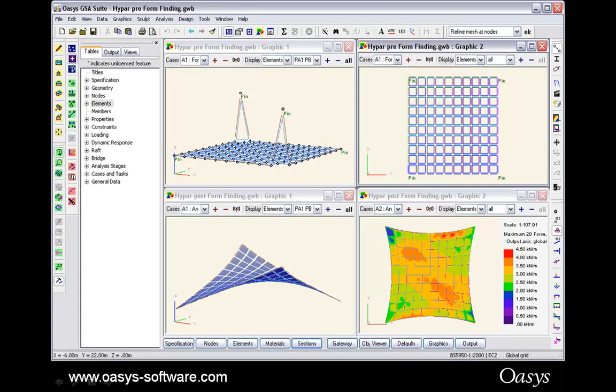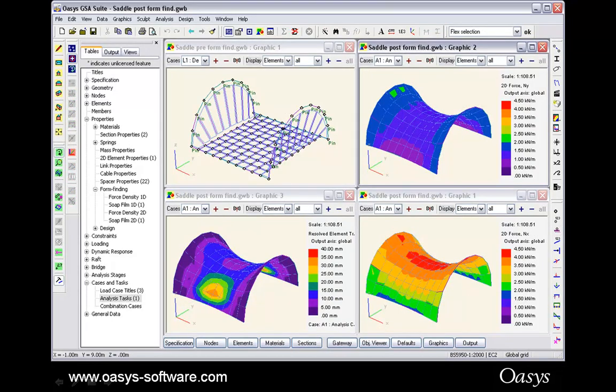Now, as GS Relax, or GSA, is a large displacement non-linear analysis, you only need to get the initial geometry right. You see in this high pass structure, we pin the four corners and have the edge cables, and the form finding does the rest. Likewise for this barrel vault, for the arch parts, fully pin the nodes, which is purely for the form finding, whereas the cable is free to move, and the end result is the shape.